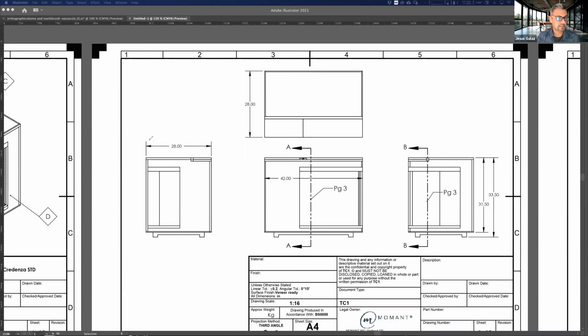The dimensions themselves: an arrow leading up to a lead line that goes up to the object, but it doesn't actually touch the object, right? Whatever product it is, these lead lines do not touch. If it is an arrow that's inside of the object, it can go to the very limit of the object on the inside, so that one can touch with an arrow. If it's a lead line, it shouldn't touch the object. You should steer clear of that.